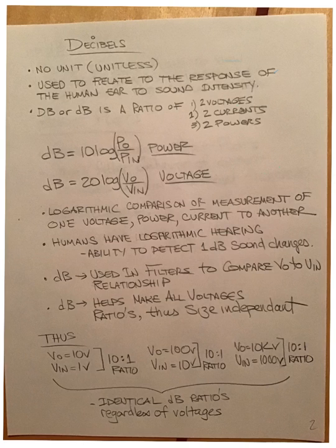The decibel is used in filters to design filters and compare outputs to input relationships. People want to know if a frequency is fed in, what is coming out. They want to know what kind of filter it is, where the cutoff is, how many volts happen at the output at a certain frequency, and how quickly the filter is squashing the signal.